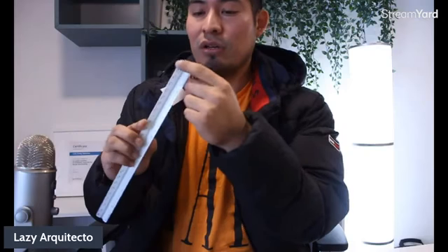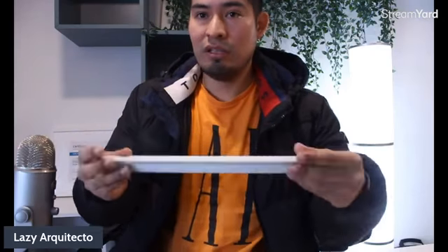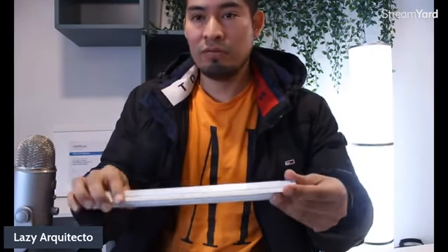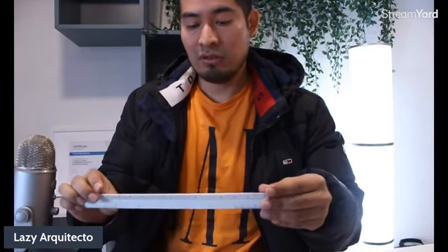It says 1/4, and he can simply measure the floor plan and know the correct sizes of things like walls, doors, and so on using a scale like this. So that's the reason why we need to print to scale or PDF to the correct scale on your viewport in AutoCAD.